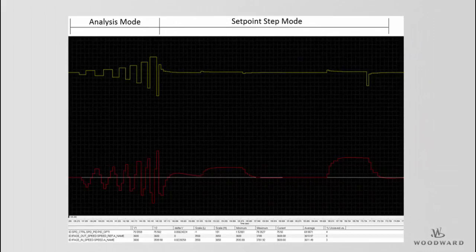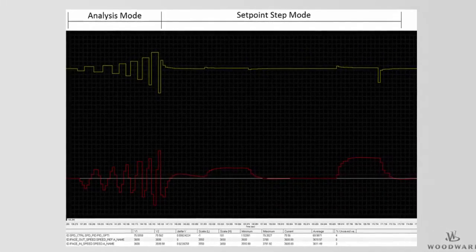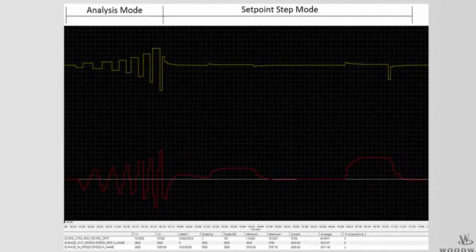To calculate optimized system dynamics, small and progressively larger adjustments are made to the valve demand in order to measure the turbine system. The optimizer routine remains within user-specified process and valve movement limits to ensure that the turbine system remains within acceptable operating limits.